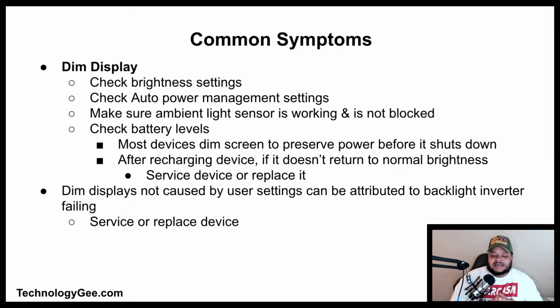Also, dim displays not caused by user settings are usually attributed to the backlight inverter failing on the device. So if this is the case, you will have to service or replace that device as well.